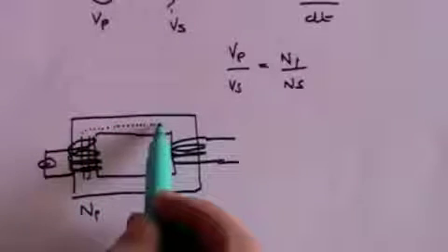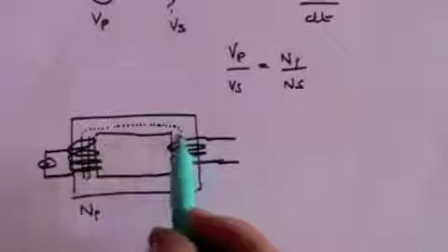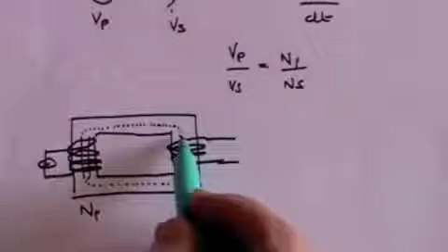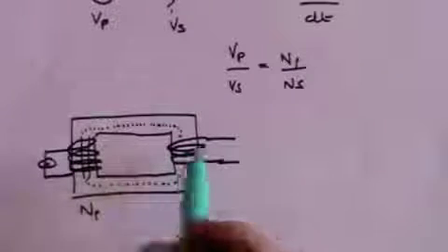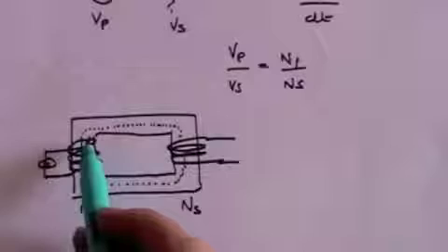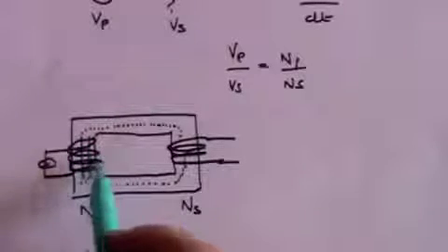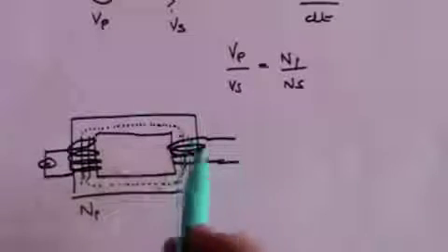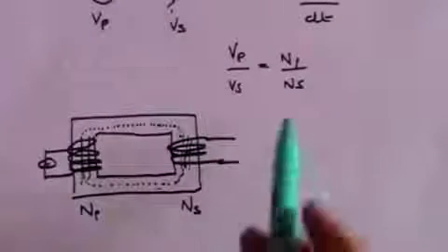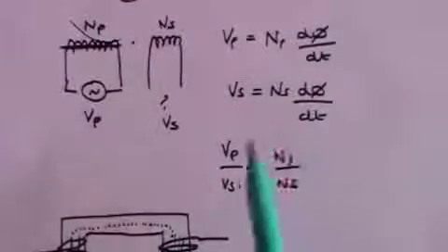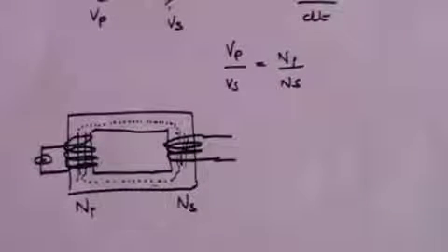So in fact, effectively the iron core carries the magnetization right the way around, and you have the same magnetization, and indeed changing magnetization, because this field is constantly changing backwards and forwards. That's going to have the same effect in the core, so that you get broadly the same change of magnetic flux on this side, and therefore these two are broadly equal, and thus this formula does hold true.